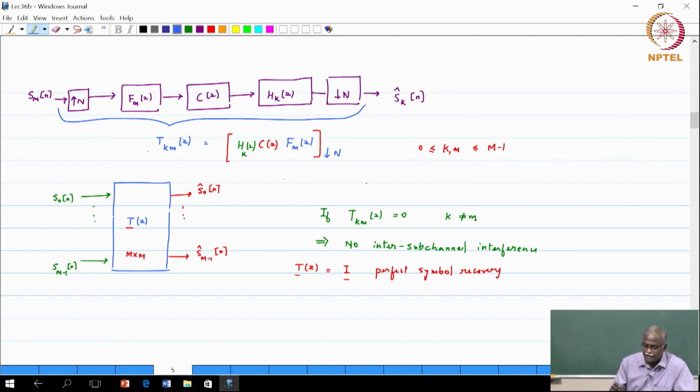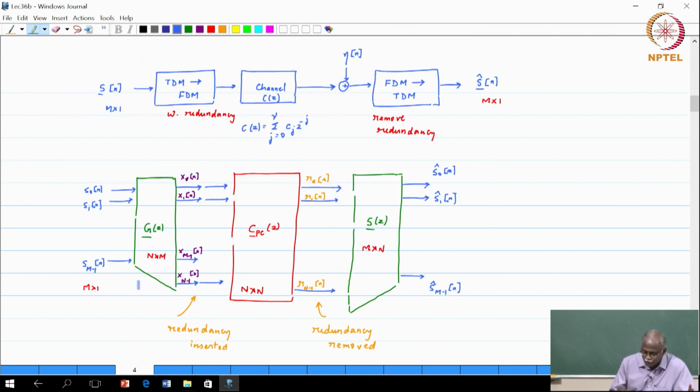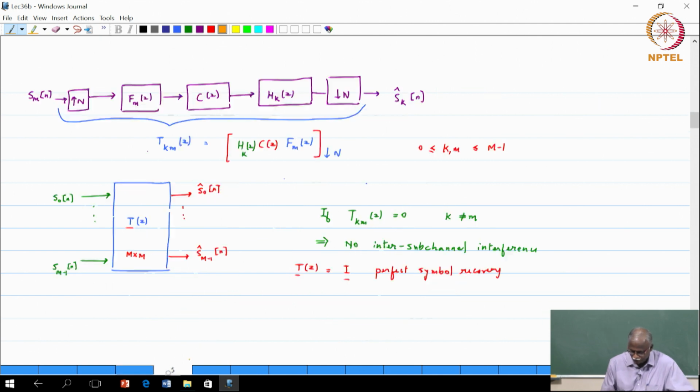Okay. So, in this process we did not explicitly mention it, but we have used type 1 polyphase decomposition in the synthesis filters, and we have used type 2 polyphase decomposition here. Again, maybe just make a note so that the overall notation, everything sort of will fit in together. Okay. So, how are these elements obtained? You can go through, we have derived these results. So, we will not spend more time on that.